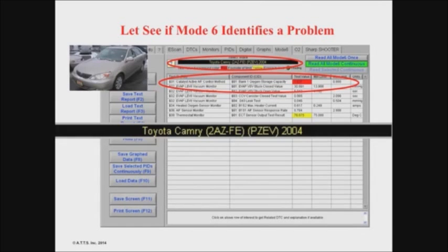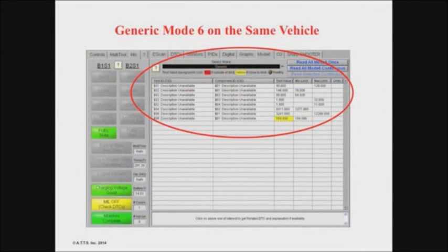Now, the other thing we like doing, and he didn't match the car up, went in generic. I didn't pick Toyota when I went into a shop. And I just did this because I do training programs and I'm curious. Notice there's no red box up top. The yellow on the bottom we had on the previous screen is yellow here. Notice it's not defined, telling me what anything is, correct? Now, why do I put this in here? Because you're going to see on the next slide, when you do pick the right number, it says catalyst deterioration, not oxygen storage, which really is similar, but the engine group was not the same engine group that the guy should have picked.